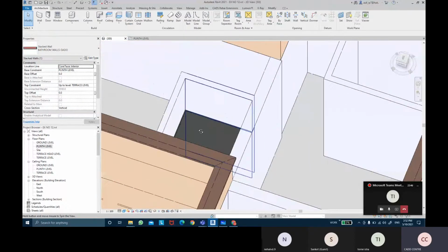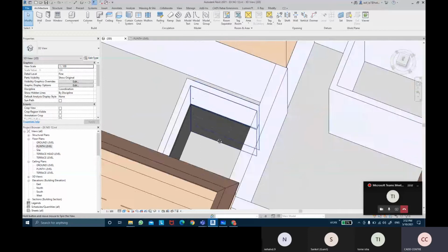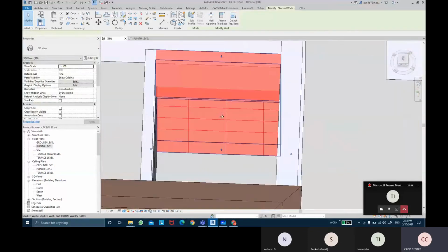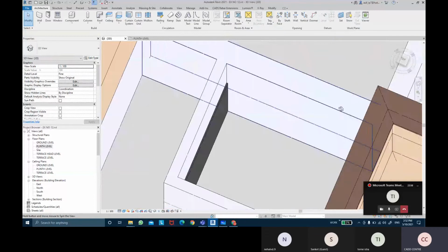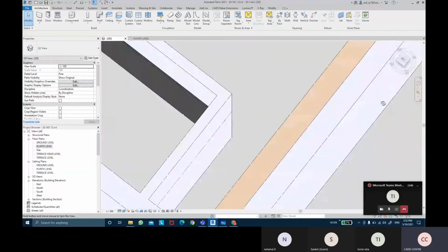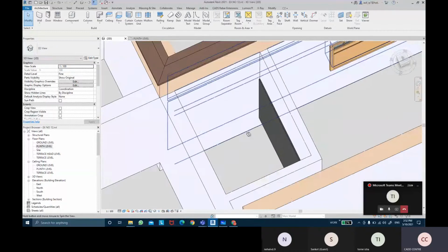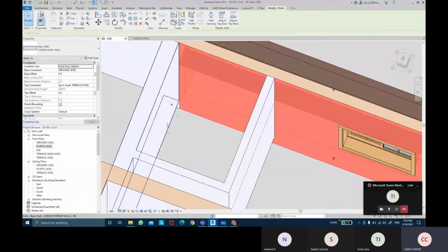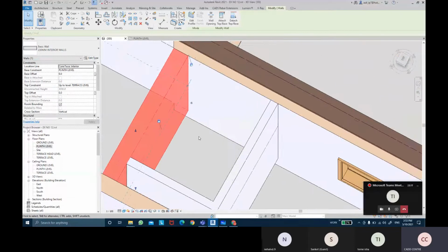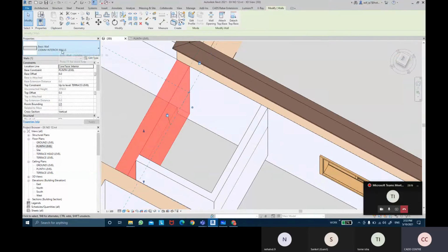in the bathrooms we have that tile up till the height of 2100 mm, and then the rest is the paint wall, on these two sides. But on this wall we don't have it, and now we have it on this wall as well. So we can create another basic wall with interior finishes.